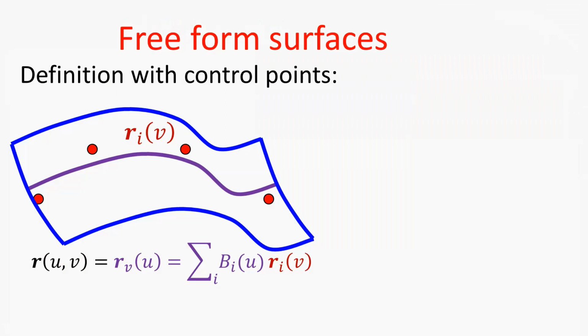So far we traced back the definition of surfaces to the definition of curves, and these curves can be analytically defined curves or free-form curves specified, for example, with the strategy of Catmull-Rom splines, Bezier curves, Lagrange interpolation curves, anything we want. Free-form curves are defined by control points. Using this approach, we can also say that all surface definitions will require the specification of control points from which the curves and finally the surfaces are built.